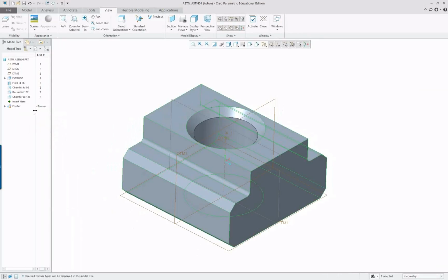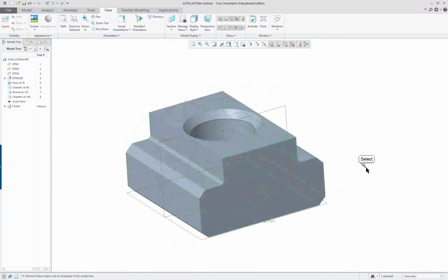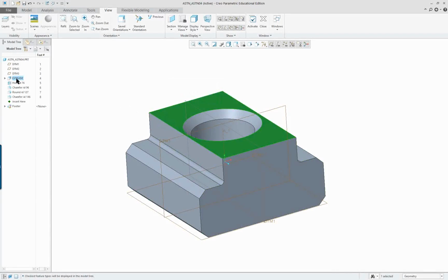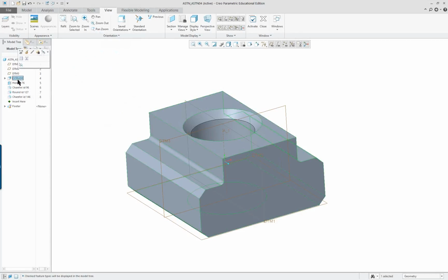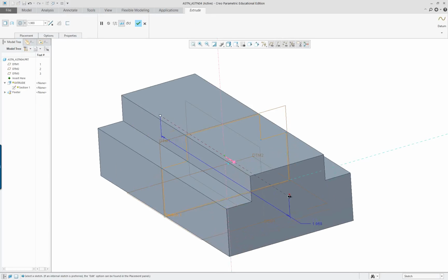So I'm going to slide this one back, keep a little bit of it open. And in this case here, I'm just going to select something. It doesn't make any difference. You'll see that it selects that particular first feature that I have. And right mouse button, or I can just select it and move my cursor here, and I'm going to pick Edit Definition. I would say 70% of the time you're using Edit Definition for something after the original geometry has been created.